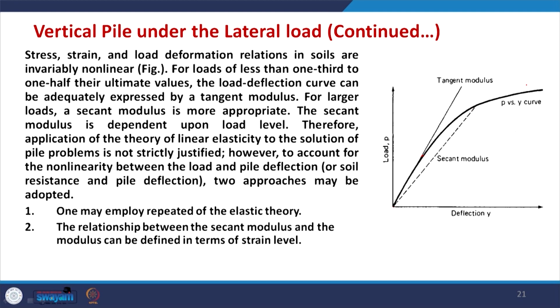Therefore, application of the linear elasticity solution is not justified, and we need to account for the nonlinearity of the load and pile deflections. For this, we may either employ repeated application of the elastic theory, or define the relationship between the secant modulus and the modulus in terms of strain level. These things we are going to discuss in the next part of the presentation.